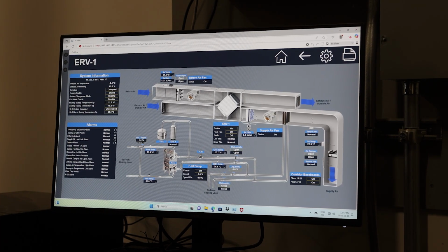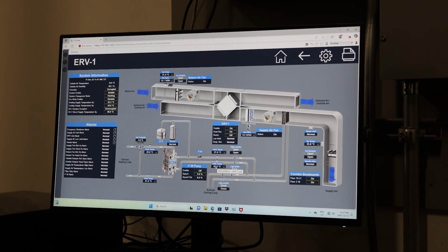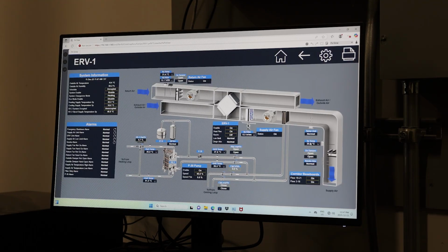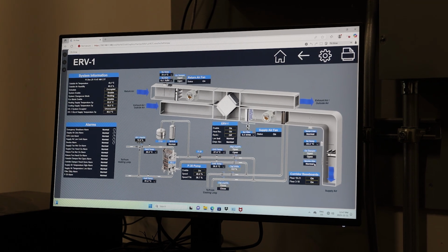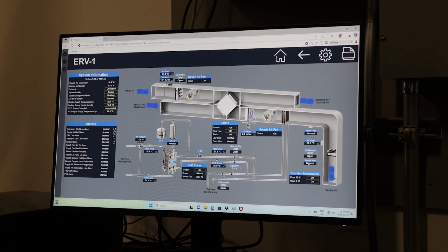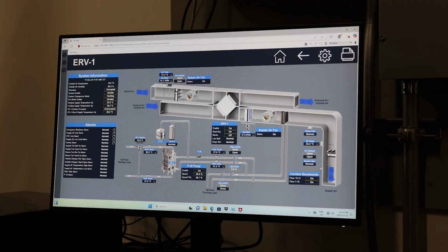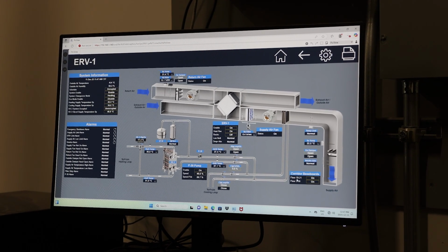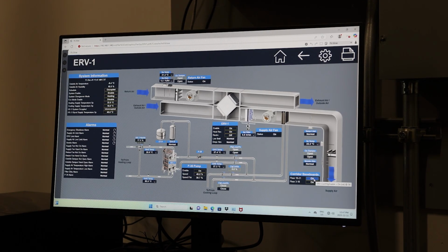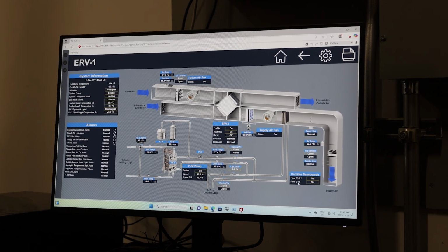On here, we also monitor the supply temperature and the return temperature on the heating coil. And downstream of the coil, we have a low limit and the supply temperature sensor, and also the isolation damper. After that, we have a smoke alarm that is being fed from a fire alarm panel. Then we also have full baseboard heater. The baseboard heater from 19th floor to 20th floor, that's the command on here. And from 3rd floor to 18th floor baseboard heater, the command is right here.